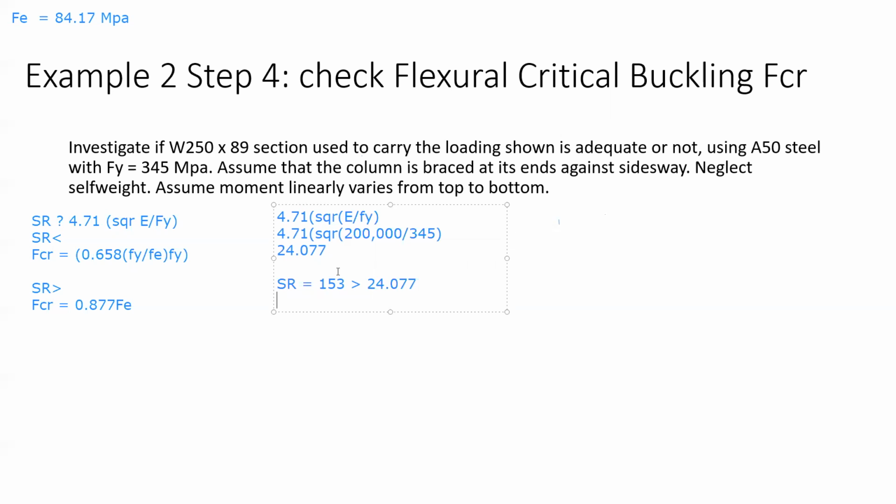So the formula we will use is Fcr equal to 0.877 Fe. That is why we calculated Fe earlier.